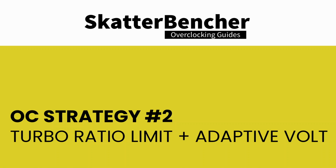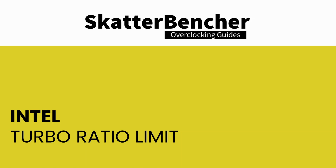In our second overclocking strategy, we finally get to overclock the CPU cores. And for that purpose, I use two fundamental Intel overclocking technologies: the turbo ratio limit and adaptive voltage mode. Intel turbo ratio limit is a technology that regulates the CPU core frequency based on how many cores are active.